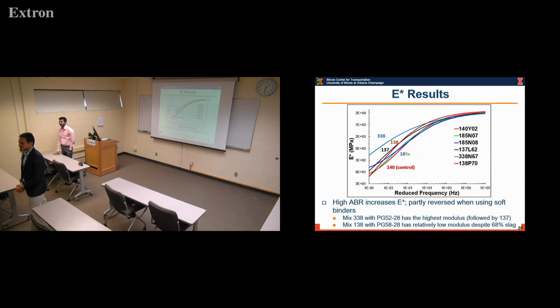Jose, regarding Singhi's comment, I think your fracture process zone can be interpreted as an area of dissipation of energy. Because the fracture process zone is larger, we're dissipating more energy, and that could explain the more ductile behavior. That's one thing, and remember the strain magnitude.